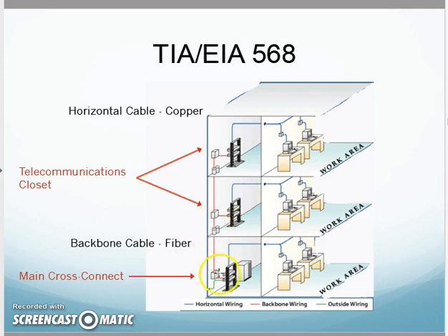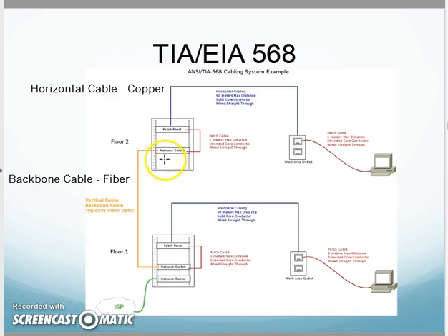But it's also used between my floors because fiber optic is made of glass. Glass is an insulator, so if I have an electrical short here on this floor, it won't travel through my backbone cable down to here and do damage to this switch, because this fiber optic is a glass insulator between these floors. So that is good for electrical isolation between my floors. And I remind you the same thing here. From my patch panel out to my work area outlets, copper horizontal cable, and the cable going between my switches, fiber optic typically. That's what I'm going to run into.